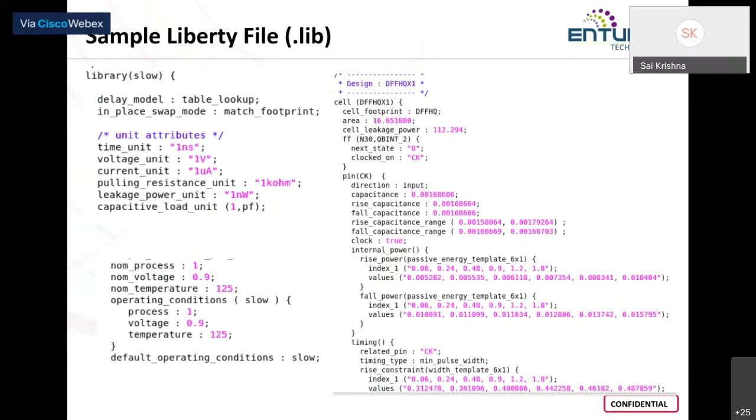So if you list out all the possible combinations where you intend to check your design, there will be one combination which gives you the worst performance and there will be another which gives you the best performance, right? There will be one combination of PVT where your charge movement is the slowest, the worst performance being the slowest charge. Please note these terms to avoid confusion later for timing analysis and physical design.